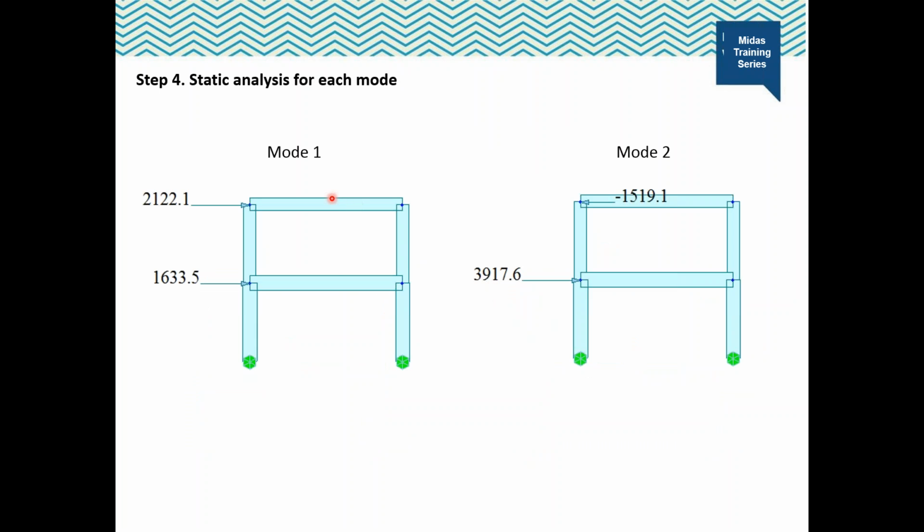As the fourth step, compute the floor displacements, story drifts, story forces, and element forces by static analysis of structures subjected to the equivalent static lateral forces for each mode.